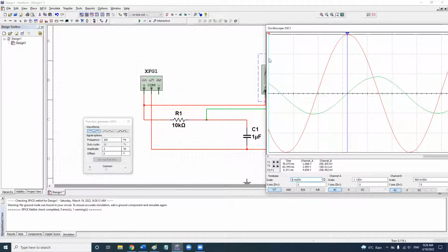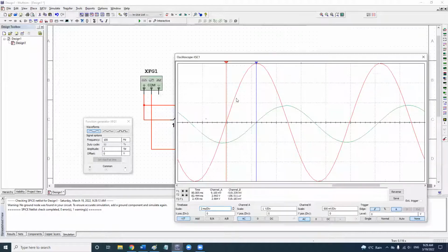So leave this cursor here. Now move another cursor to the closest one, always on the left-hand side when they both are rising, okay? You don't want to compare one rising with one falling. So you do not want to put this thing here. That's wrong. When it's rising, you compare with the nearest rising on the left-hand side of that wave, the closest one. You will be able to see it easily. The values we give in the lab are very clear, okay?